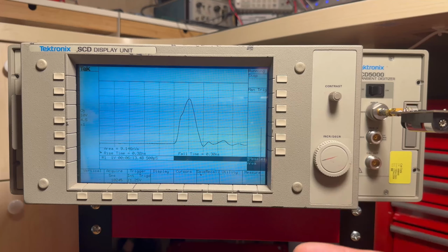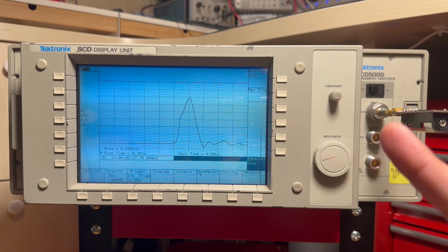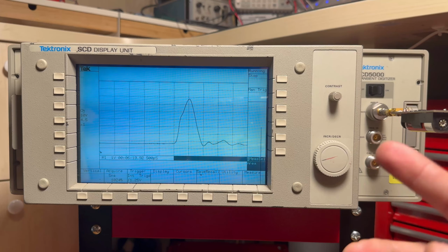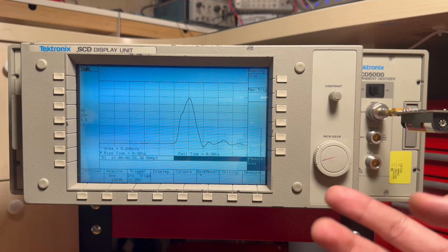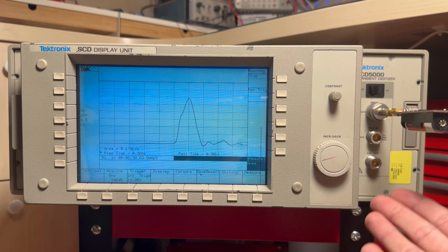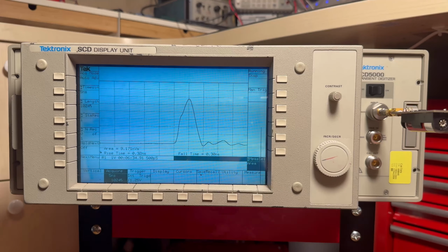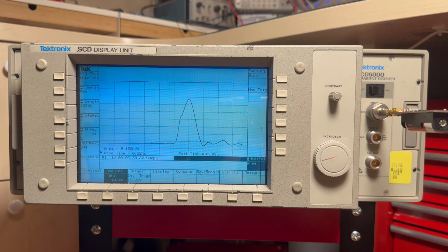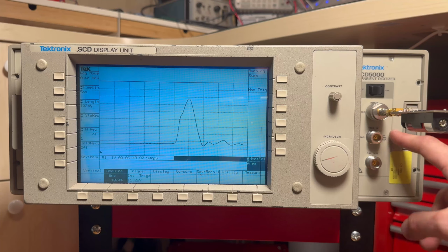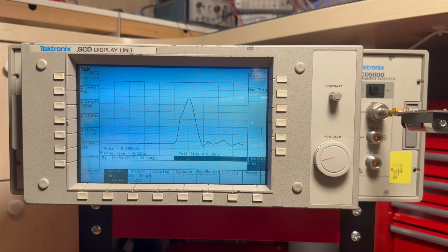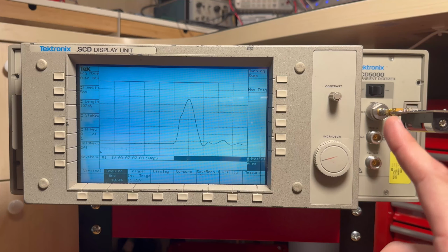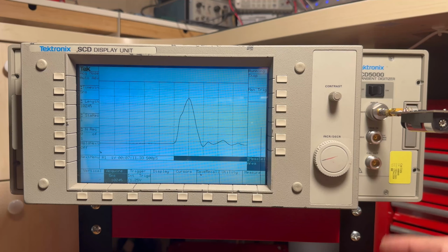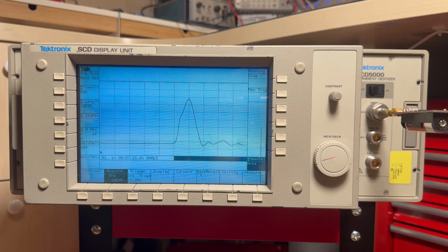It has no vertical sensitivity. The SCD5000 has the same basically input channel as one of the channels of 7104, and the same vertical amplifier and stuff like that. So 1 gigahertz of bandwidth, same digitizer concept. It's got very little in the sense of trigger, so it's just got a trigger edge, either falling or rising, either internal or external trigger, which is one of these connectors here. And it's got a calibration output, and it comes as standard with N connectors, so none of that BNC or whatever. You could get an option, long gone, long obsolete, to have it with SMA connectors instead of N connectors. I think that was the 1F option, whatever.